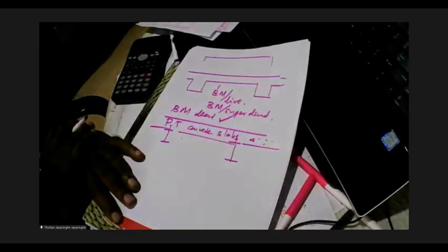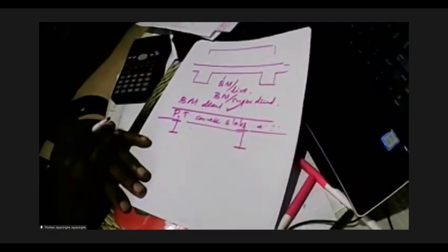So you can design a continuous slab like that. That's possible. So this is a likely scenario where in a steel building you can consider having a pre-stressed concrete slab. So the beams are running in all directions and you are supporting the slab directly on it. So this is the kind of situation where you can easily use a PT slab of thin section and the floor to floor height can be easily controlled. Is it okay, Bashika?